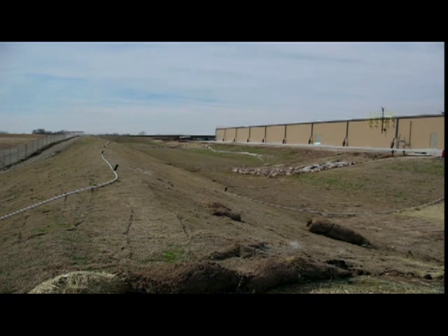This is a site behind, you can tell what that building is, I'm going to say it. It's several years later, so it's okay. This is at a Walmart site. Walmart has gotten very intent about providing these types of structures, reducing the amount of sediment and stuff. We got a guy here that did a lot of these designs for Walmart during his tenure at an engineering firm, and they got serious about it. And so you can see they've got inlet structures there, that rock in the middle of the picture. The outlet structure is designed a certain way, and they really pay a lot of attention at these sites now.